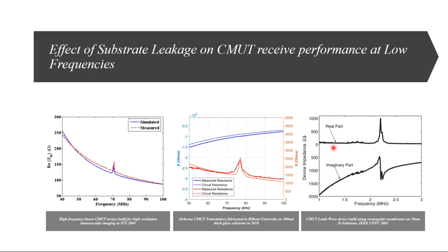So yeah, even if you have lower order Lamb wave modes, symmetrical or anti-symmetrical, A0 and S0, at the operating frequency of CMUTs, you still don't have a flat baseline. But one comment is that if it's only the Lamb wave modes in the solids, then they do not create very large negative sloped baselines like over here. Okay, that means you have shear or longitudinal elastic waves instead of just Lamb wave modes, which create the tensile stresses as such.